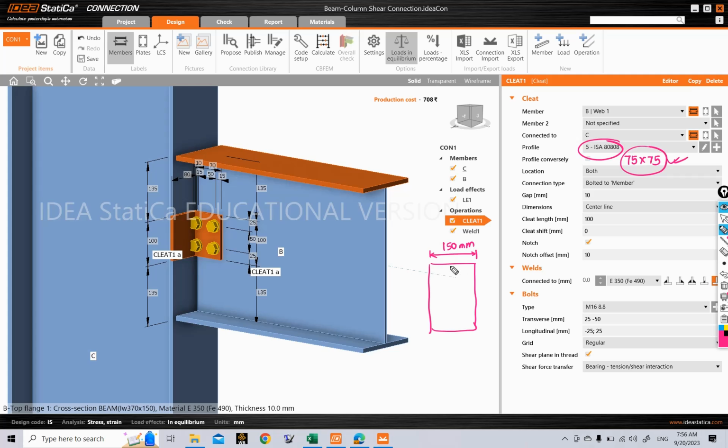First, there is a certain thickness of the beam web that is being attached here. Let me just draw this much, not this part. This web of the beam that we are attaching to the flanges of our column has a certain thickness, and we are assuming that thickness is 6 mm. So if this thickness is 6 mm, what is the space available here? The space available here will be 150 mm minus 6 mm, divided by 2. So this will be 144/2, that means 72 mm.